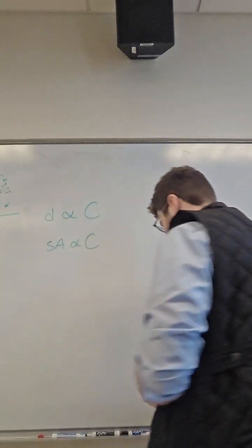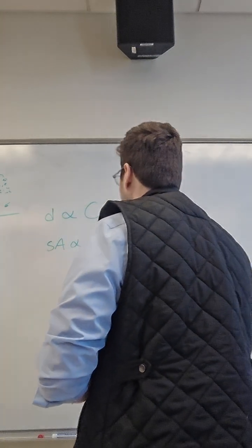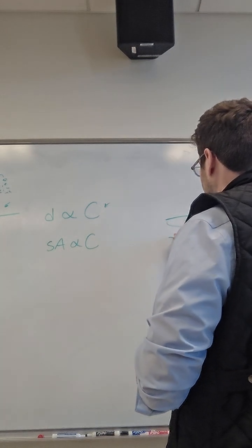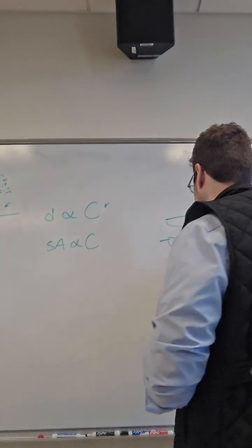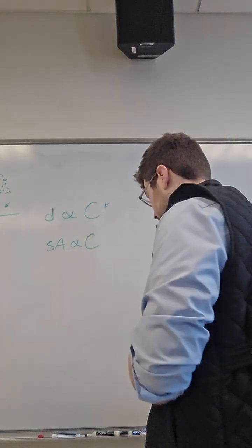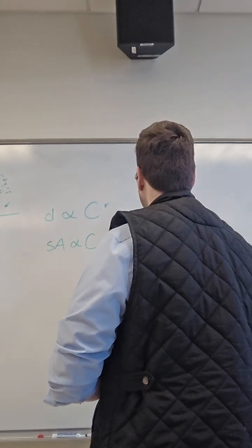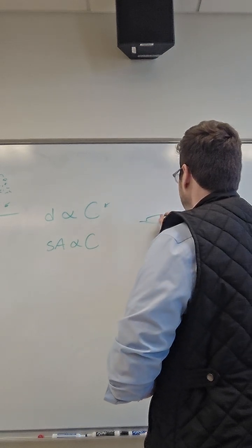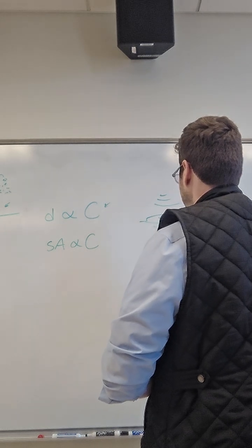Sensors that are capacitive in nature, for example microphones, all they do is look for a change in capacitance. For example, a material that is deflecting, like this, even if it's not a piezoelectric material, or actually, let's do it where it literally is a capacitive sensor. One example of a microphone, I believe called an electret microphone, is that we have a hanging eardrum element here, literally like a drum, so sound waves come in and they will deflect the drum, just like our eardrum.